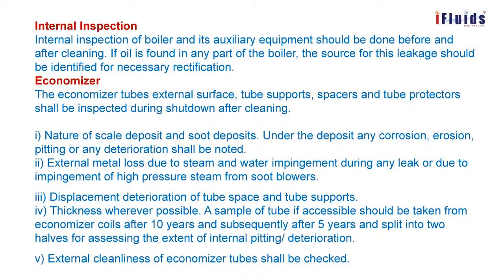External metal loss due to steam and water impingement during any leak, or due to impingement of high pressure steam from soot blowers. The soot blower is nothing but injection of steam inside that area to dislodge the carbon or coke deposits.